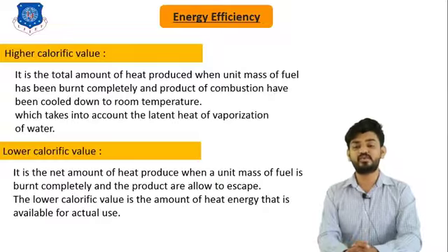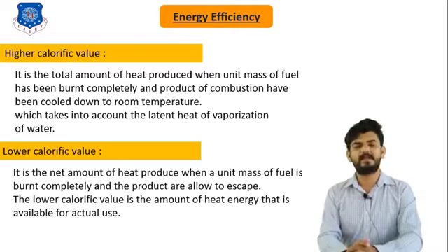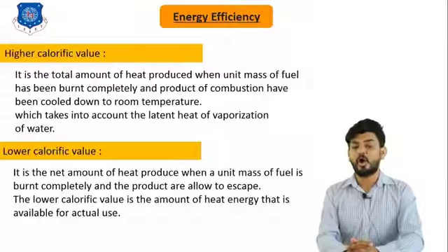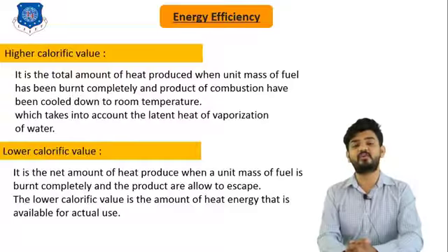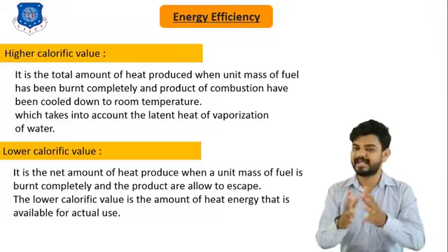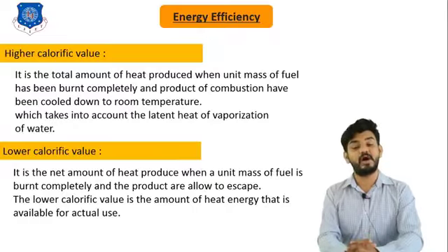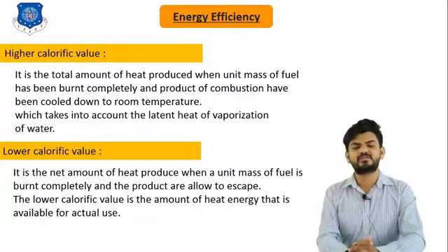So now let's move to the second type of calorific value, and that is lower calorific value. It is the net amount of heat produced when a unit mass of fuel is burned completely and all the products are allowed to escape. This is the main and important line for this definition: the products of the combustion reaction are allowed to escape. The lower calorific value is the amount of heat energy that is available for actual use. So this was all the definition and properties of fuel related to calorific value.